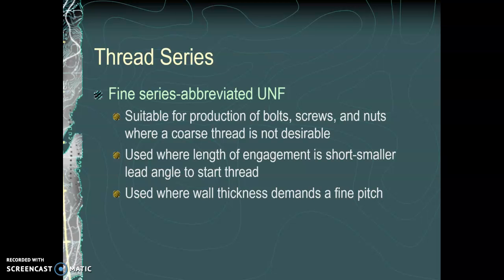So that's what it means when it says the length of engagement is smaller. So when you are perhaps drilling into a cylinder or a pipe or something where you have a limited amount of thickness, those fine threads are going to be more desirable. Of course, it does then subject you to more potential seizing due to corrosion.